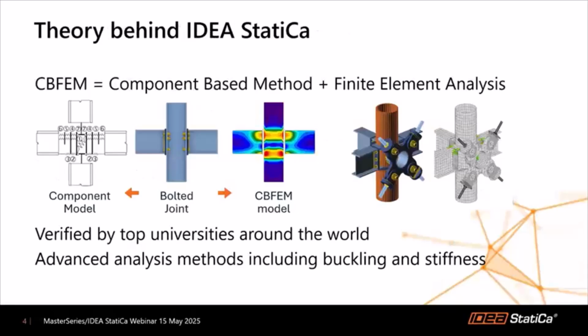And a little bit about the theory behind IDEA StatiCa. It still complies with Eurocode because it uses the CBFEM method, which is a synergy between the component-based method and a finite element analysis model. So if we look at a simple bolted joint, for instance, that is comprised of the various components of the model, which are the members, the plates, the welds, and the bolts. And these are modeled as either shell elements or specifically nonlinear springs.